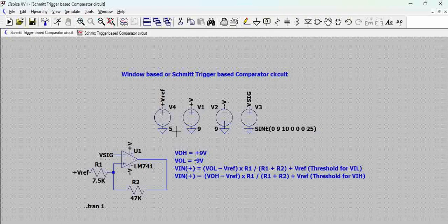So that's how you can play around, and you can build the circuit and use it for your applications based on the signal. And here, understand that we haven't considered what the impedance parameters of the signal are. We have considered an ideal signal input which has zero output impedance. And here also, the op amp output impedance is considered zero. We are not considering its impact. It might be there in the model.